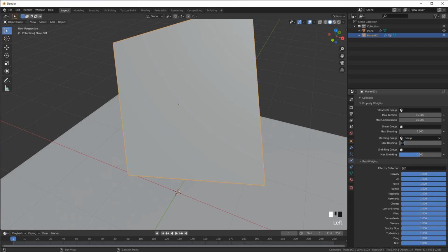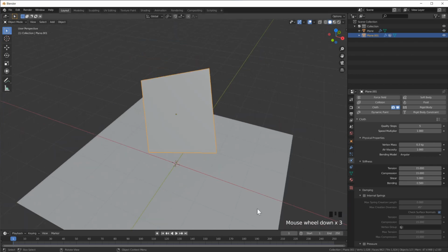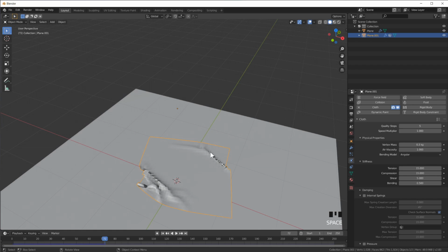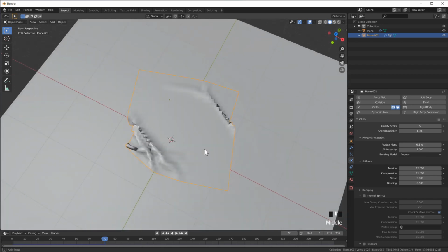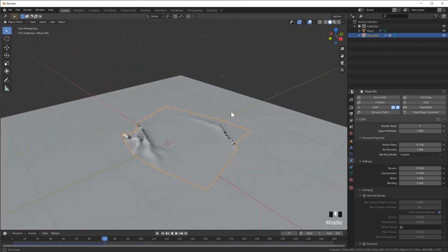And here we want to resist bending. So instead of 0.5, I'm gonna set this to 5. The rest of the cloth is using a bending of 0.5. Now what does that look like? You can see we get wrinkles on the outside, but this center part here resists bending, so it wants to stay flat or straight. It doesn't want to have wrinkles in it.